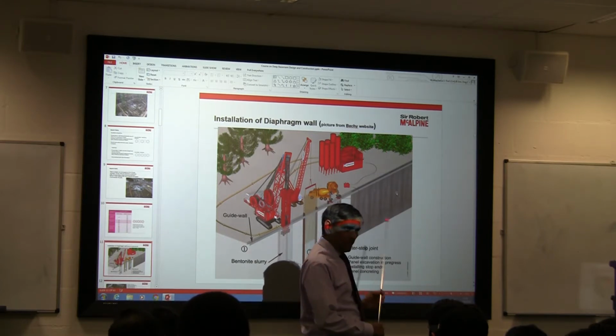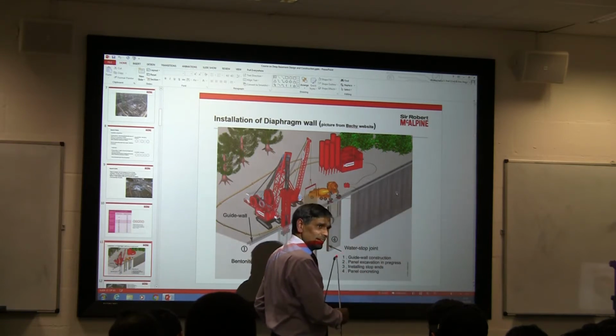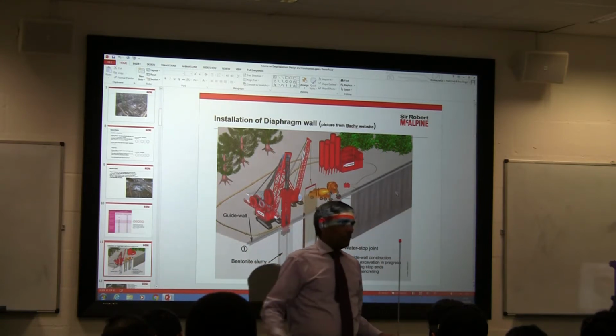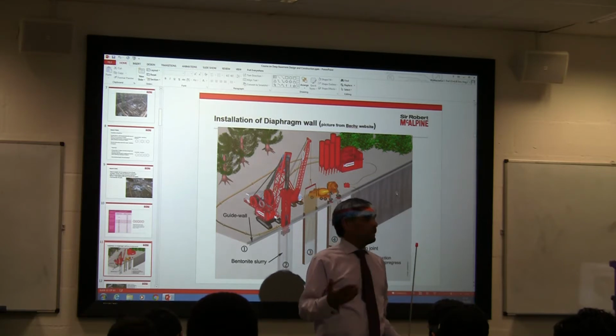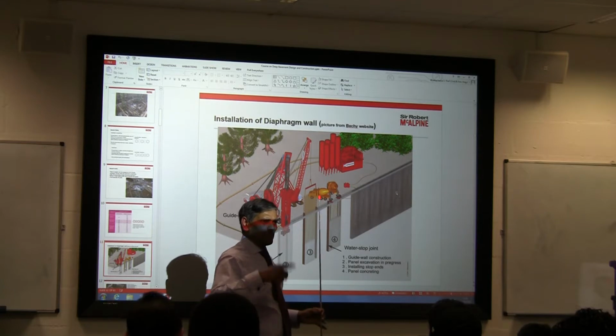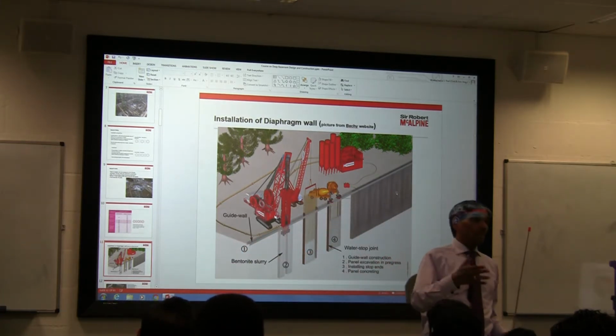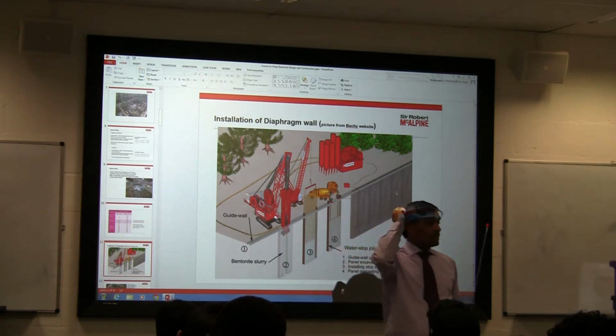operation. Because if you look at the panel, I have to pour full panel concrete volume in there, right? So that may take probably 48 hours. So you got to go take permission. So you got to choose the length of the panel in terms of your deliveries, in terms of approvals, in terms of whatever the council is telling you, you can't do more than 24 hours routine.